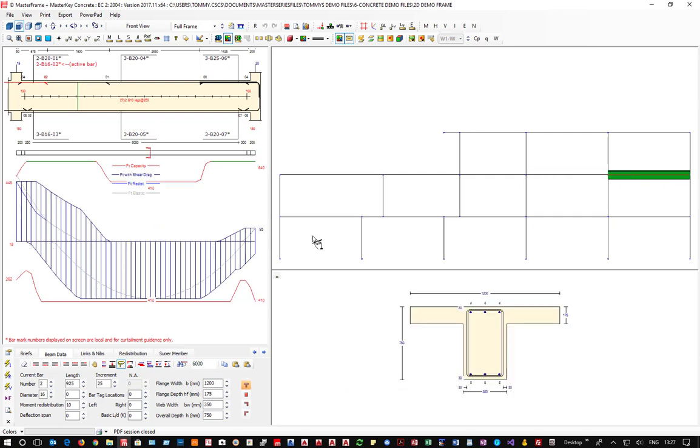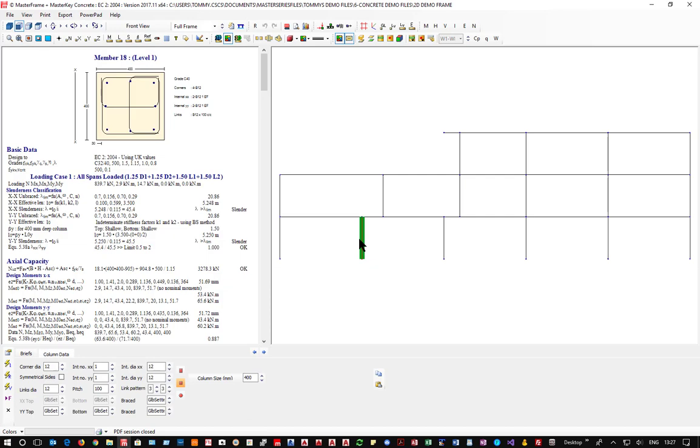So that's our beams. We also can do the columns, so little square columns, very simply, and it's classified as slender, and it's using the K1 K2 factor for its effective lengths and classification as recommended in the National Annex, because there is no guidance in the Eurocode itself.